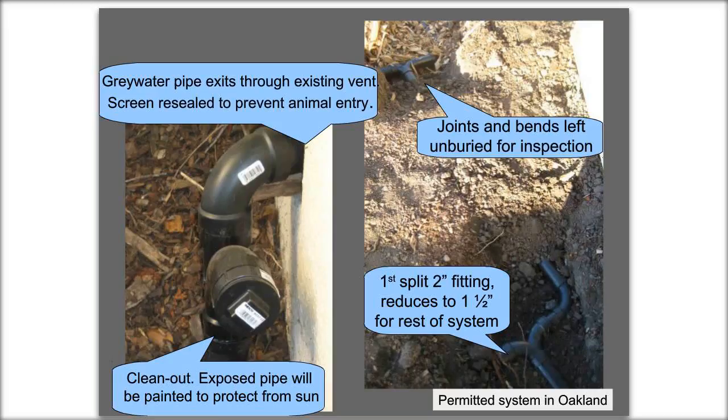But many of them also understand that if you leave straight runs of pipe unburied in the sun for a long time, it can warp. So you would ideally ask if you can bury straight runs of pipe. But some of them say no, and you have to just strategically hold down the pipe before the inspection. Otherwise, your system can get out of alignment.